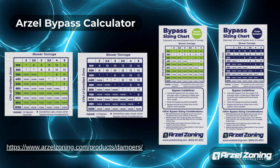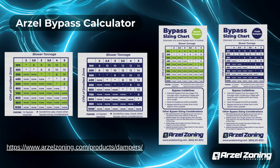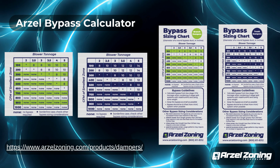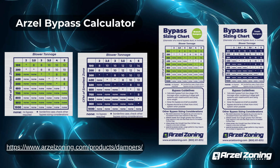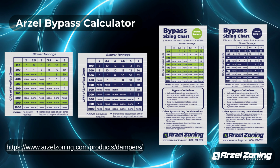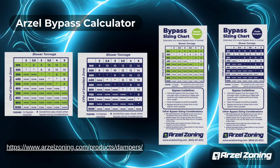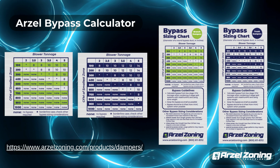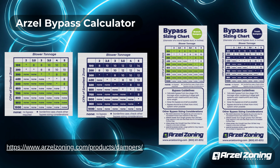On the flip side, if my smallest zone that I'm doing a calculation for is a close zone, or maybe it's not flex and it's hard metal pipe and it's a close zone. So in other words, I'm doing a calculation for my smallest zone being the primary bedroom, and it happens to be right above the mechanical equipment, and my supply runs are only 4 to 5 foot long and they're solid metal pipe.